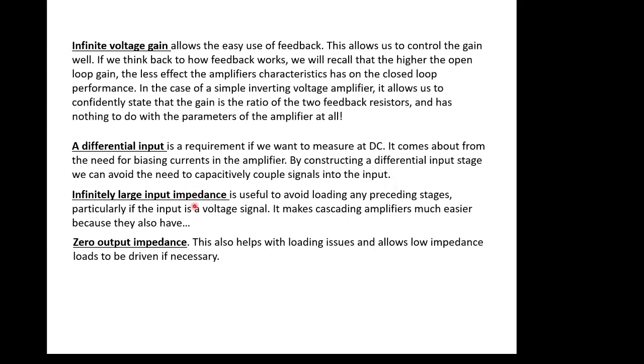And a large input impedance, which means no current goes into it, is useful to avoid loading any preceding stages. It also makes it easy to analyze things. If you think back, virtual grounds only exist because of infinitely large input impedances. But it makes cascading amplifiers, which means bolting system blocks together, much easier, because if you also have a zero output impedance, when you connect a zero output impedance to something that has an infinitely large input impedance, there's no loading at all, and therefore it's a perfect system connection.